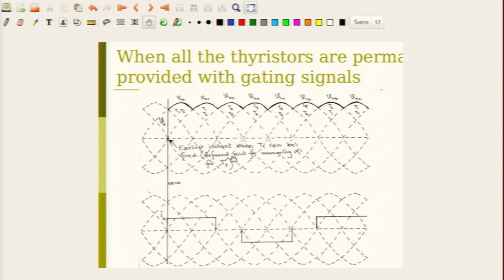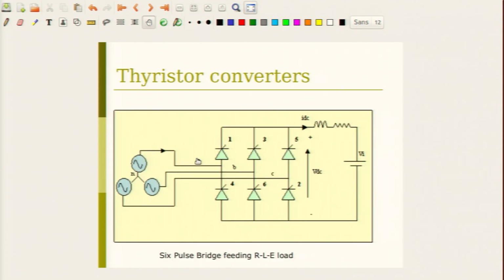Now, remember that if you have got a 3-phase bridge diode rectifier, each diode turns on just when it is forward biased. So, in fact, you will find that T1, T6, all of them turn on just at this point, okay, because the thyristor which is continuously fired is in fact like a diode. Another aspect which is interesting is that when thyristor T1 conducts, then the current IA, this current IA here is equal to the DC side current.